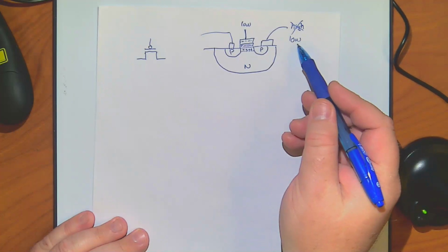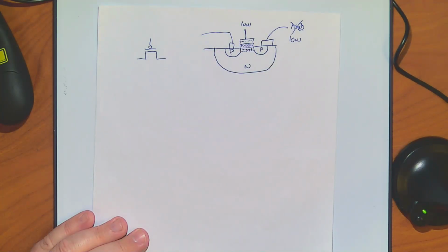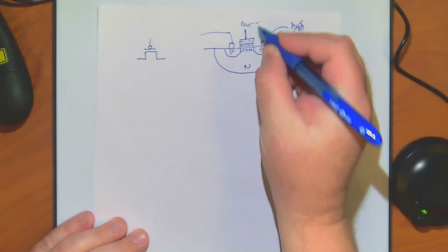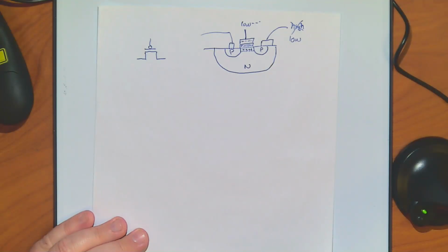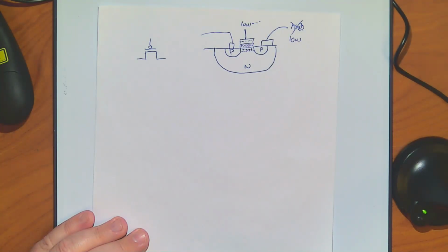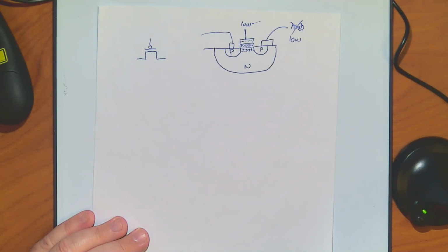What happens if what I'm hooking is low and I'm trying to pass it through from this side to that? Well, this has to be lower than that. So this has to be really, really low. Right? But I can only get down to ground, which means this can't go super low. This is going to have to stay above it by at least several tenths, somewhere in the high tenths up to a volt. Right? This has to be higher than that. It just has to. Otherwise the gate doesn't open.